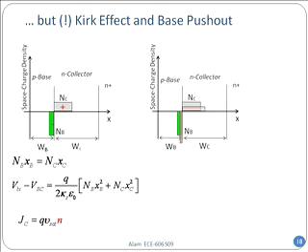This is what happens. You see the original green and the ash colored region. That's the equilibrium. But as you start putting more and more current by forward biasing the base emitter junction, your effective doping and effective depletion width changes to the magenta colored region. Why? Because when a lot of electrons are coming, the next electron will come, the next electron will come.